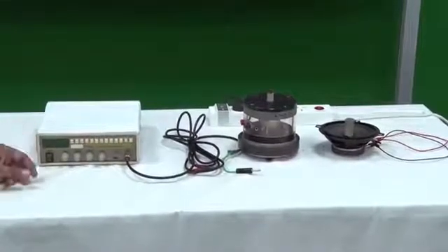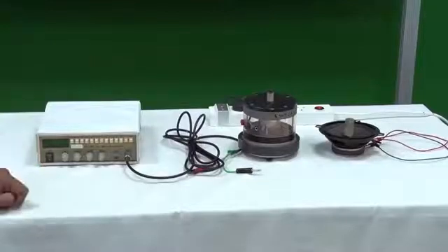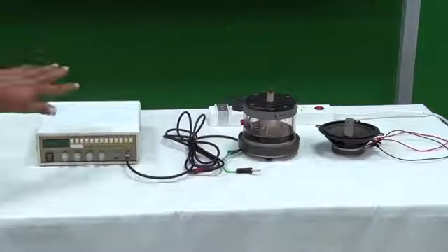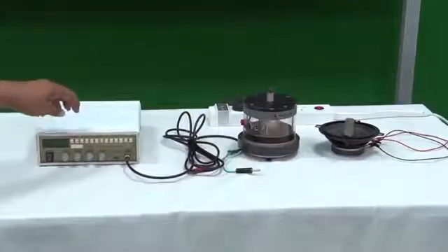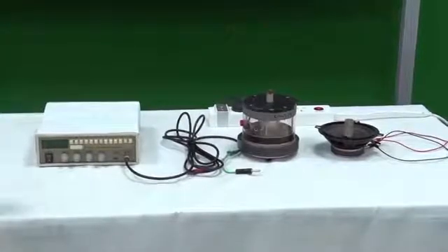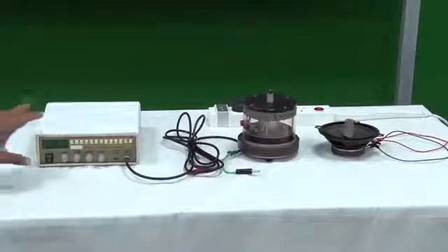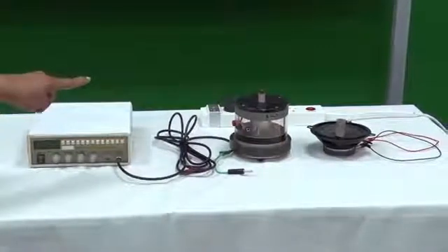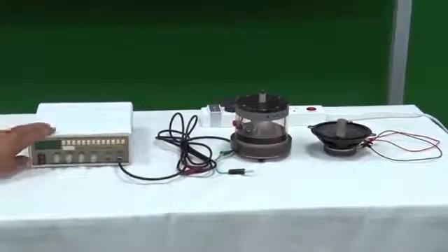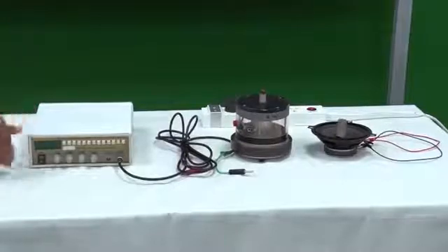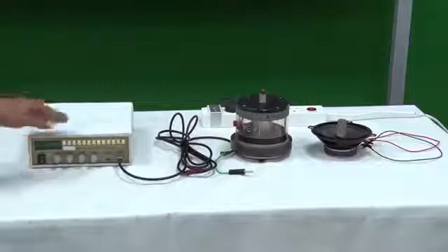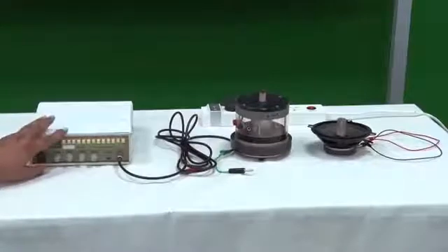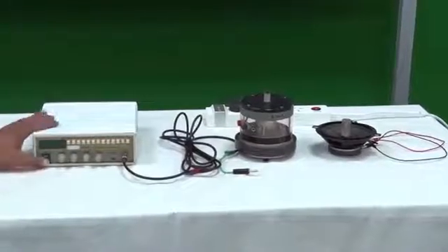So, we need DC voltages, but still we are using 220 volt and 50 hertz power, because we do all our DC conversions in this unit itself, otherwise we will have to carry batteries. So it operates on AC, but it is not using that AC, because that AC is 50 hertz only, and it is producing its own AC at a very different frequency, derived from the DC voltages which are converted from the AC from the power supply, and then that DC is used for this oscillator circuit.